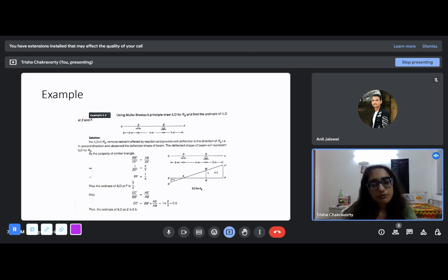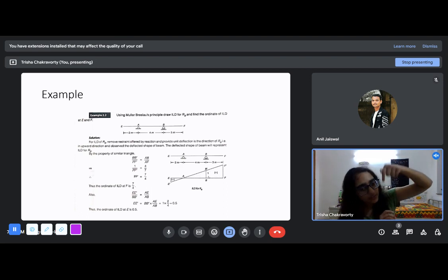Okay, and see, this one is here because this one we know not because we have given a unit displacement. This one we have to find out using our judgment. Like we know that when the force is applied at B, which is the ordinate of the ILD at this point, the reaction at B will be 1. So we know that this ordinate will be 1. We know that. And this shape we have found out. So since it's a linear profile, using geometry, we can find out these ordinates.